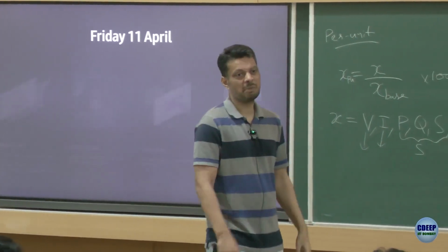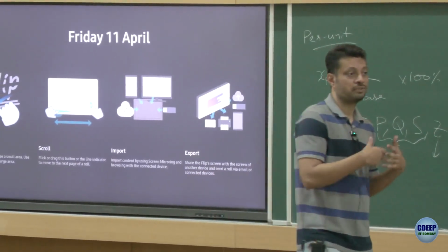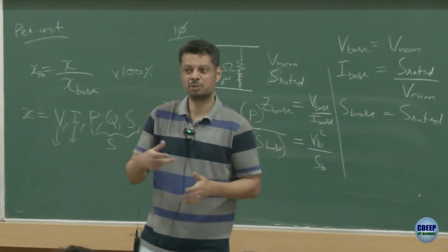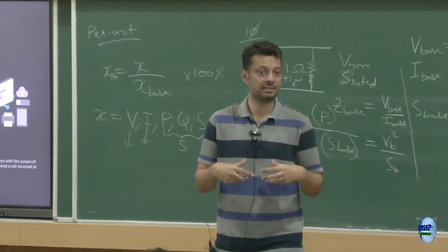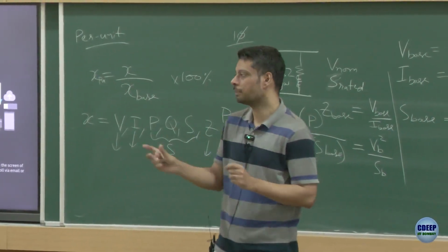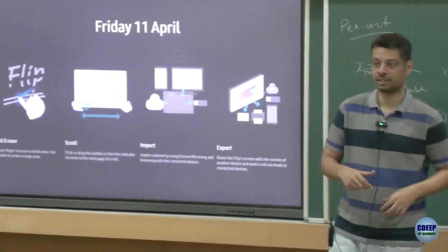Then you have to measure the grid voltage. Now the grid voltage is maybe, there is some generator producing 22 kV, some generator producing 11 kV. So if you want to standardize things, you can do all the computation on a per unit basis, right? And then you only need to multiply it with suitable scaling factors when you want to convert it into actual quantities, right?